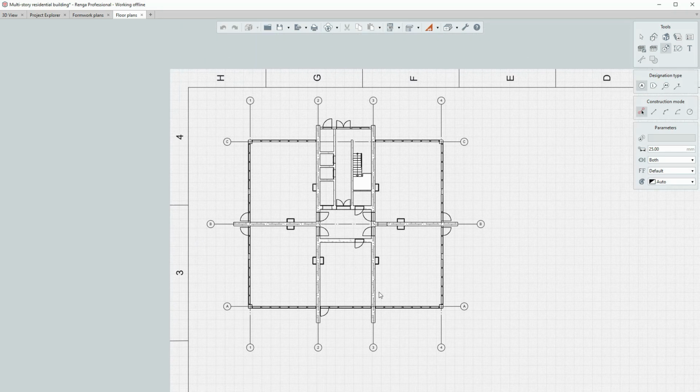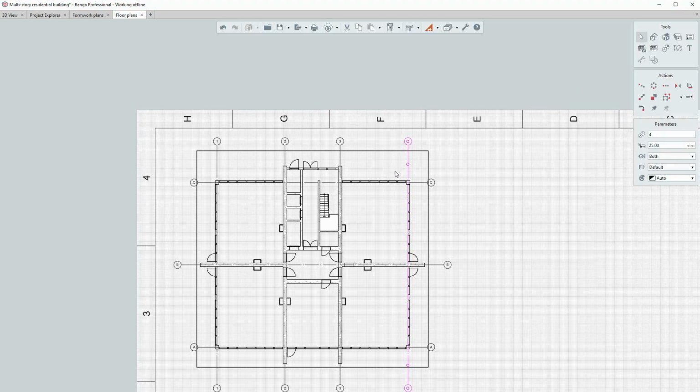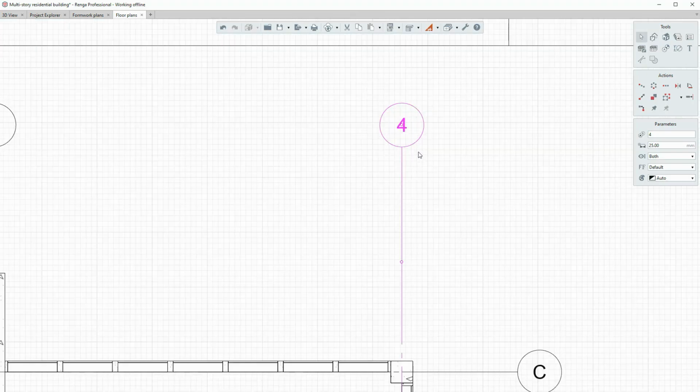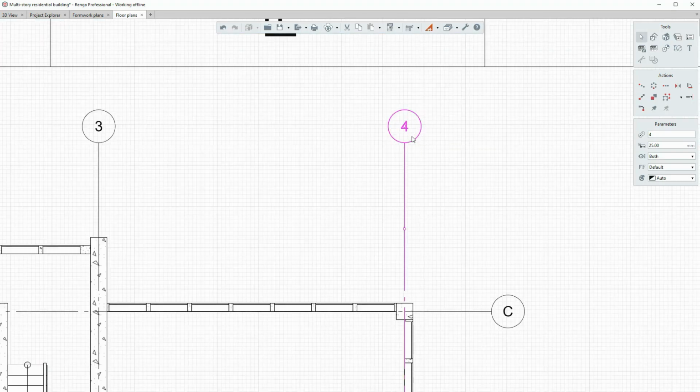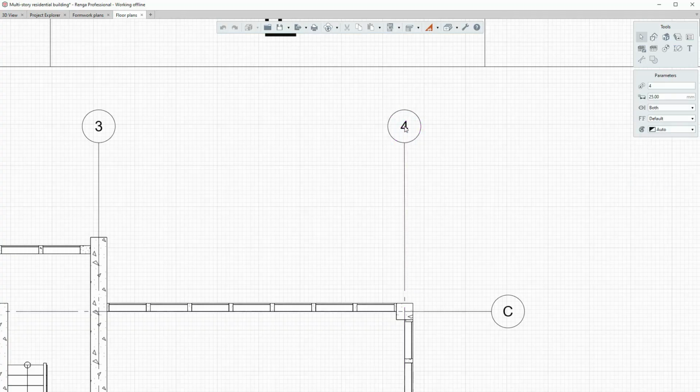Grid lines created in the drawing automatically by view will update when you edit the model. But if you move or rename the axis in the drawing, the link between this axis in the model and in the drawing will be lost. To change the position of the created grid bubble, select the grid line. Edit the grid bubble position using handle.